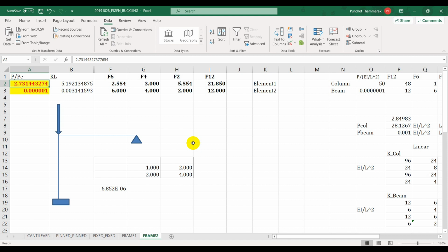So you will solve and you will get the displacement solution U. But when you will solve for the incremental force vector, so you start with small value and then you keep increasing the force, and then you have the deformation that is increasing with the force up to one point where the stability is triggered. You are close to the axial force that caused the problem. Then deformation will be no longer linear with the load. Deformation will be exponentially growth with the load, and that is the bad situation.